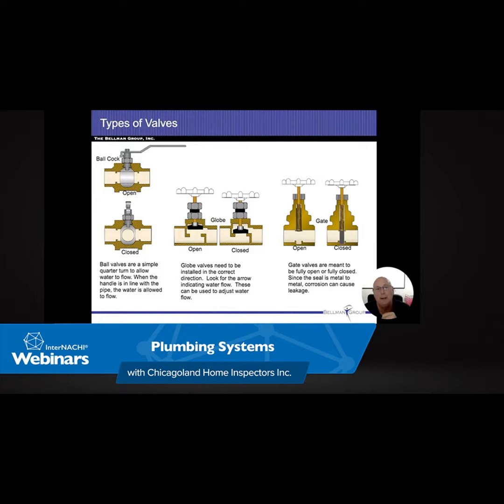Then those perforated tiles are going to be typically 10 feet apart. They're going to have perforated tubes in them that allow the water to drain through. There's going to be a whole bunch of gravel in there as well, so we can let the water drain through easily. When everything's working properly, we're just going to see a little bit of greener grass wherever these things are, because it's going to be watered and fertilized better than anybody else's.